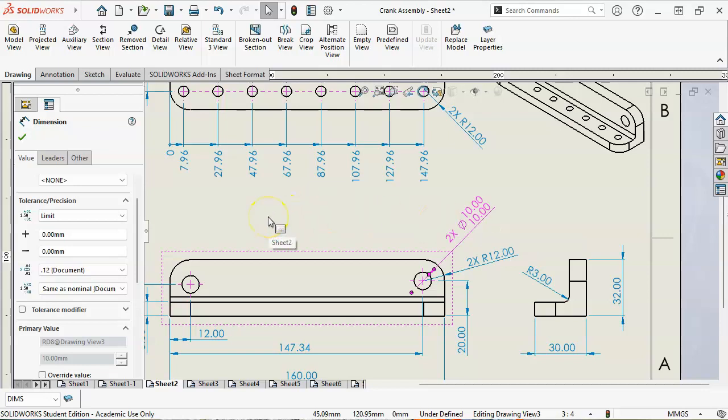So on the plus side, I wouldn't want it on the maximum material condition. On a hole, it's going to be the lower number, and on the shaft, it would be the higher number, more material, maximum material conditions. So if we were to go 0.1, that would be about 4 thousandths. That's a pretty heavy duty press.